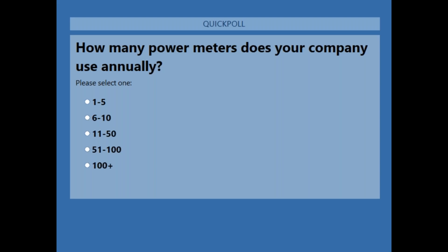It's compliant with ANSI C12.20 class 0.2, which is the standard that we use to meet revenue grade. And peak demand is one of the values that you can both log and access for a 62-day trend, or pull it off the meter into your energy management system and log it that way as well.